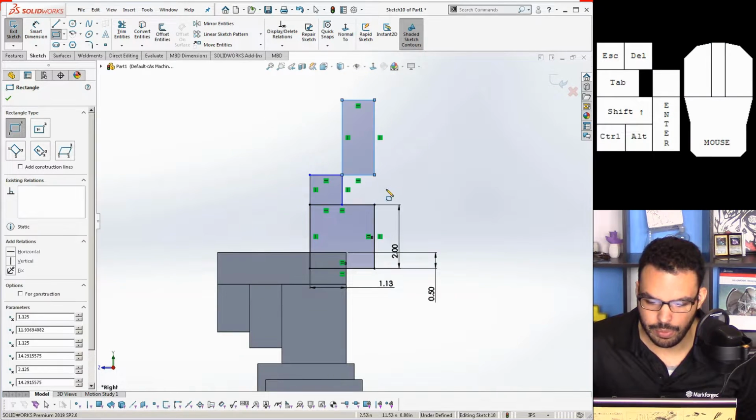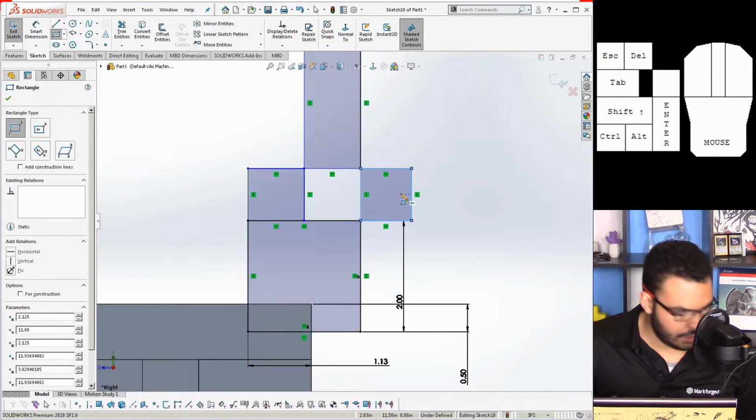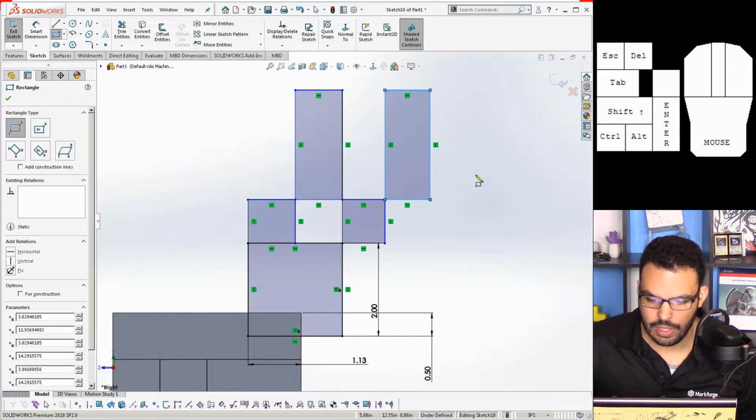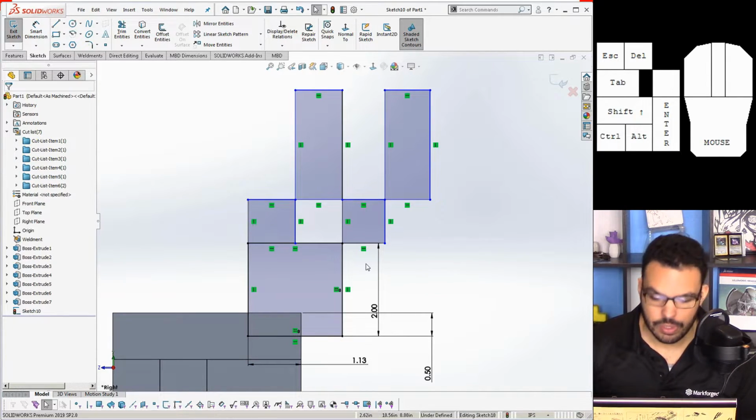Draw a rectangle from right there. Draw another thing like that, and then another thing like that. So if you use the sketch in the wrong feature, it might say something like endpoints wrongly shared, can't use a sketch, or something to that effect. And the endpoints wrongly shared refer to these endpoints where they branch out in more than 2 directions pretty much. It can confuse SolidWorks at times, but we're going to get around this by using a setting in the boss extrude when we get there.